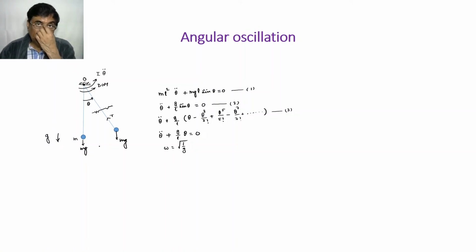So if we apply the inertial torque in the direction opposite to the direction of motion, sorry, I have shown the direction of motion wrongly, then the system will be in a virtual static state, and then you can put all the virtual equilibrium conditions.